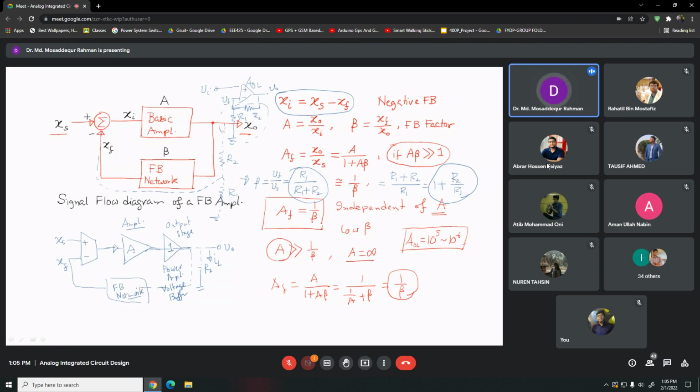In the case of op-amp, we have just 2 resistors here, R2 and R1. So we can also show it like this. We have R2 and R1, 2 resistors, and that just goes to this input side. So at the input side, this system here that takes the difference, usually we also call it difference amplifier. So this difference amplifier, then we have the basic voltage amplifier, and then we have our output stage, the power amplifier or voltage buffer.